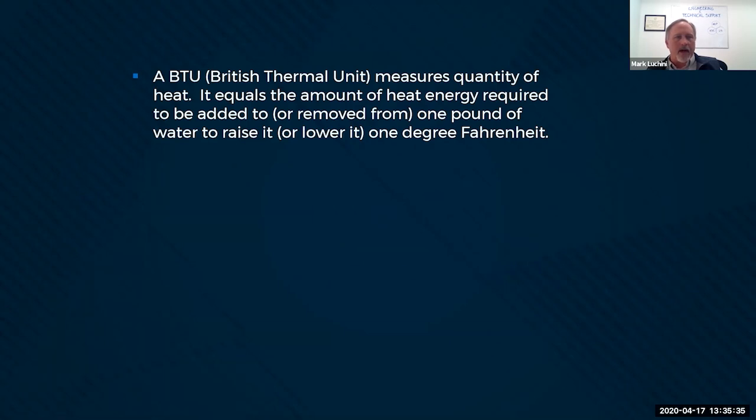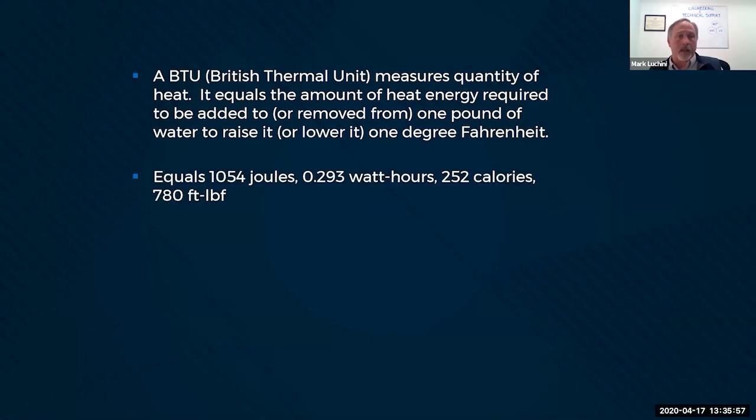When we talk about quantifying heat in the HVAC world, we talk about BTUs. A BTU, quite simply, is the amount of energy it takes to raise 1 pound of liquid water 1 degree Fahrenheit. Strangely enough, it only takes half that amount to raise a pound of ice 1 degree, which we'll see in a bit. Some equivalencies, other units that you can apply: joules, watt hours, calories, foot-pounds of force. Those are the equivalent values for 1 BTU.